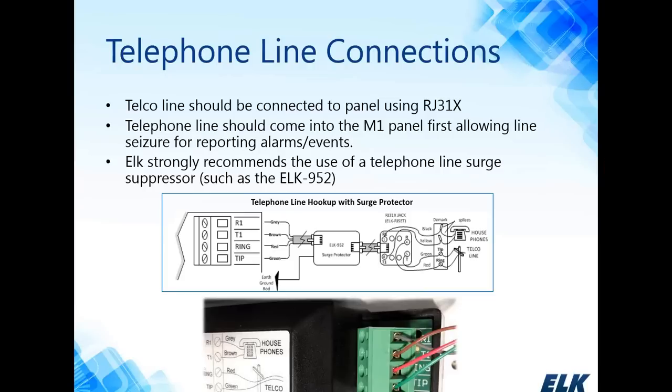And we include the ELK 952 surge suppressor in the kit. And you can see in our little block diagram here, it's real simple to install the 952. More than likely you're already going to have your RJ31X and your 8-pin modular cable back to the control, so you simply put the 952 in the middle between them.